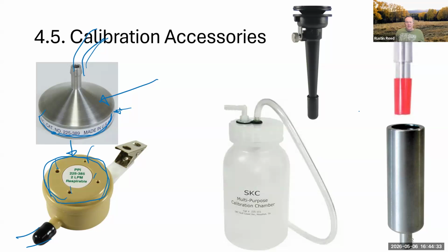I'll talk about the adapters, then we'll talk about the calibration jar. So for the Cyclone, some of them have special adapters. This aluminum one has an adapter, so this would go up and over, and you can kind of see it there. It has an O-ring inside there. That O-ring is going to fit nice and snug right there to create a seal. And it's the same idea again. So the PVC filter cassette on top of that is going to go to our pump, and the adapter.